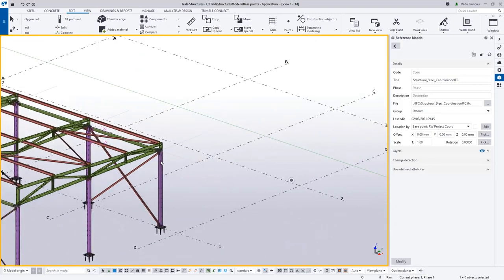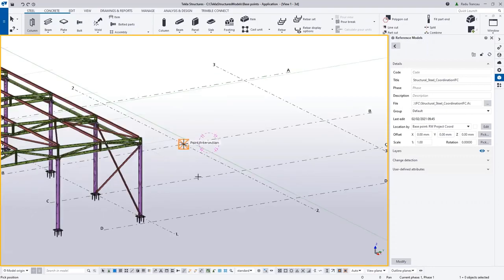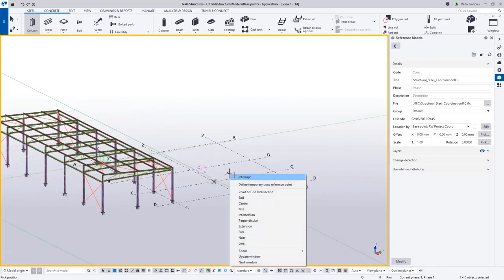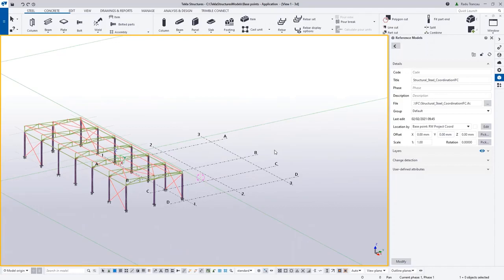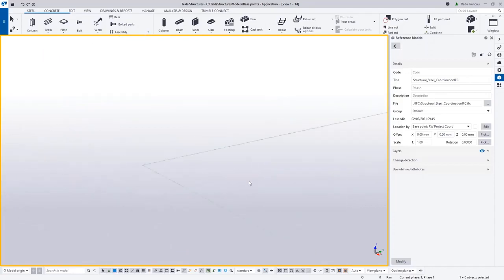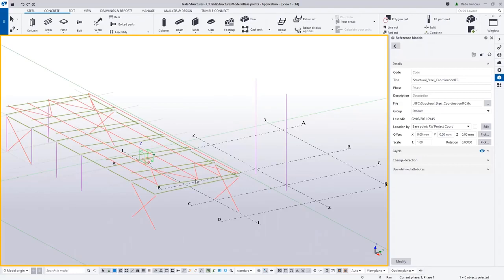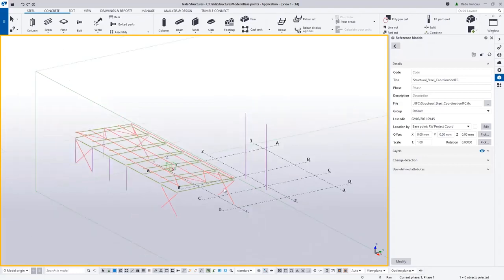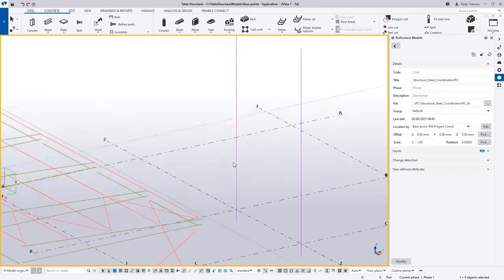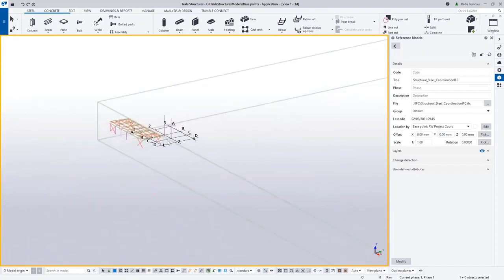Okay, so I will just try to quickly draw a column here and a column here. You can see it's not showing. Okay, so it's giving me the same glitches as before. So that's one common issue with not exporting or importing the IFC close to origin and leaving this huge work area with objects which are very far away. A quick fix to this one.